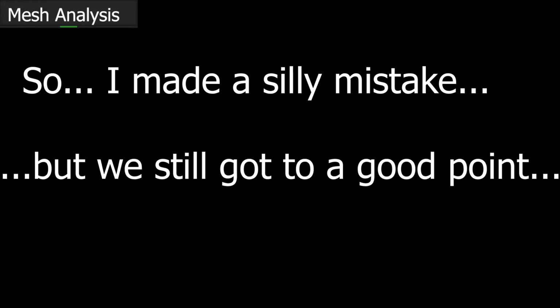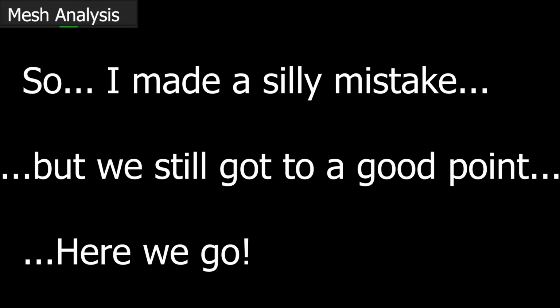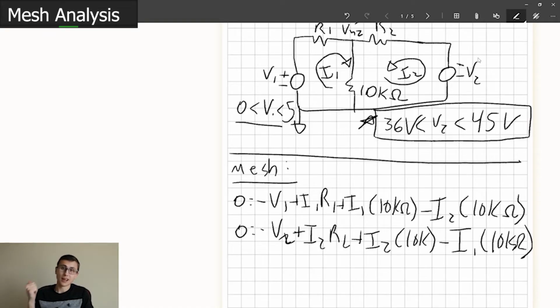Easy enough. But that poses a problem for this specific design example because I1 and I2 are not fixed. Those are variables. We don't know what those are going to be because we have voltage sources, not current sources. And so the current in either loop is defined by the resistors. So every time we change the resistor, we change the current. So we get into this recursive problem, since we're designing with voltage in mind, right?